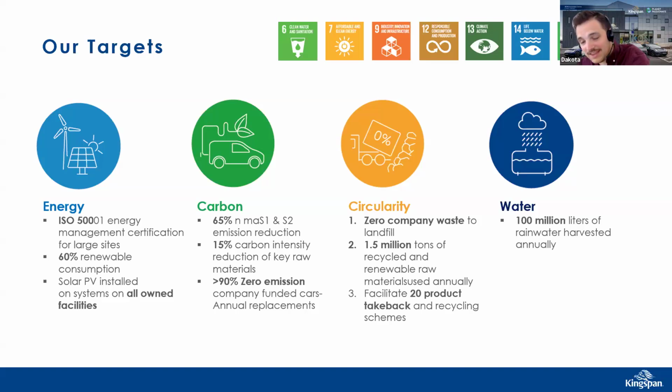On top of that, we actually have a take back program. At the end of the insulated metal panel's life, this is essentially steel, insulation foam, and then steel. So it's a sandwich. We can take that insulation on the inside when we take these panels back after the building has been decommissioned, mulch it up, and use it as aggregate for concrete, which makes it lighter weight and more insulative. The steel's recycled as well, meaning that product gets another chance at life, which is really cool and allows us to give you opportunities to pursue LEED credits and wellness credits through environmental product declarations, EPDs, or life cycle assessments, LCAs.